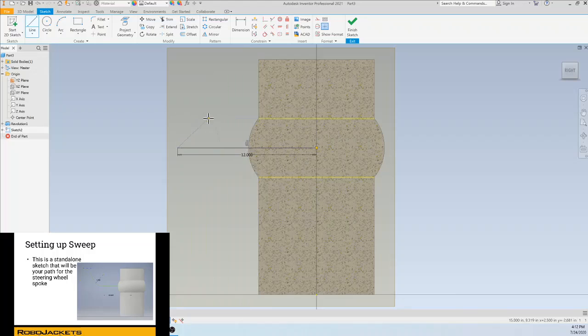And then again, with these arcs, there are a couple different ways you can do it. You could create circles and then trim them down. Or you can make, let's see here, I believe what we want is a tangent arc. For some reason it's wanting to go there, which is odd, so I'll just mash the escape key. There we go. Yep, and we want to set the radius as 5 inches and the angle is 90 degrees.